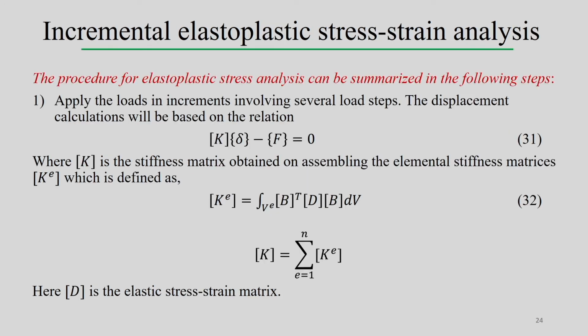Now, how incremental elastoplastic stress analysis can be done. Before that, the procedure for elastoplastic stress analysis can be summarized in the following steps. The first step is to apply the loads in increments, involving several load steps. The displacement calculation will be based on this relation.